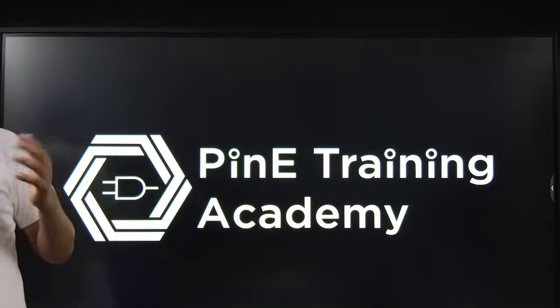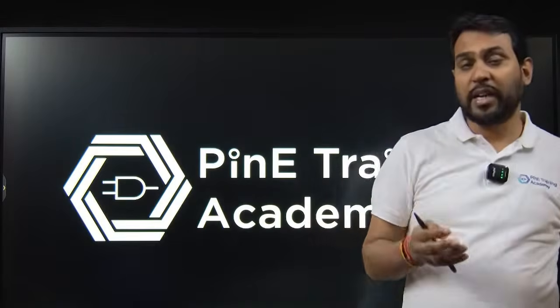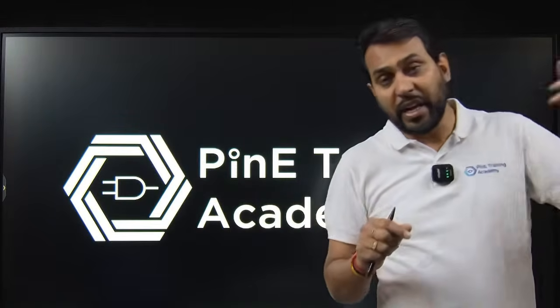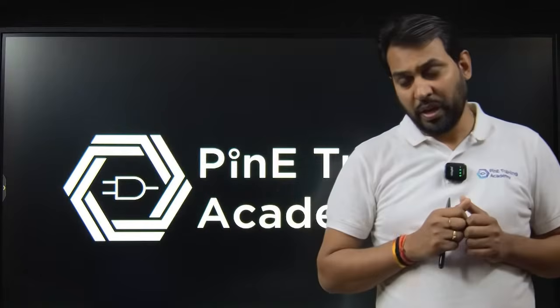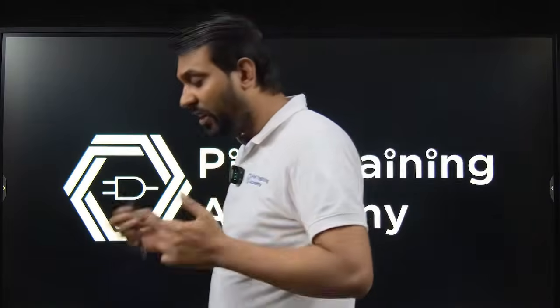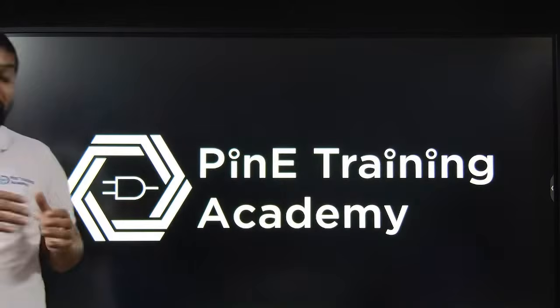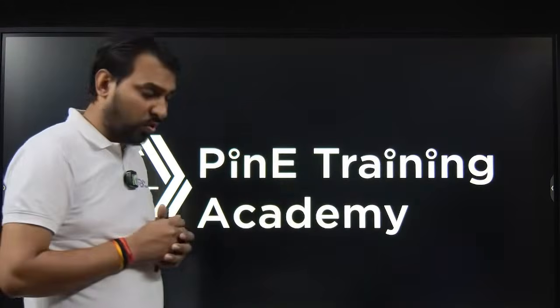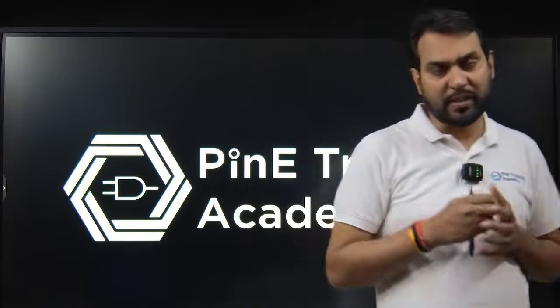Now, KCL we discussed: the algebraic sum of the entering current in any node is equal to the outgoing current, or you can say that in any node the entering charge is equal to the leaving charge. There is no charge staying on the node. That is, KCL works on the principle of charge conservation. Similarly, in KVL, the algebraic sum of voltages in a loop is equal to 0. Algebraic means the direction, plus or minus.